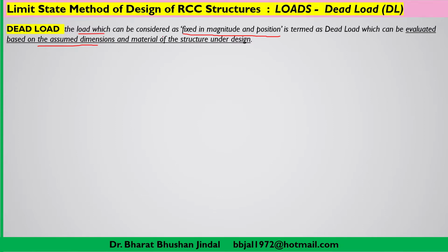That load, which is fixed in magnitude and position, you will term as dead load, and its calculation depends on the dimensions which you have assumed as well as the material of the structure under design, whether it is concrete, steel or any other material. Based on the unit weight and dimensions of that material, you will be able to work out the dead load.